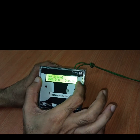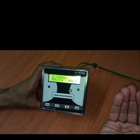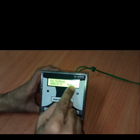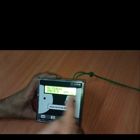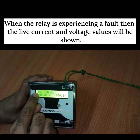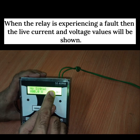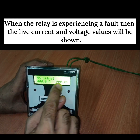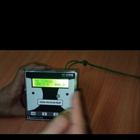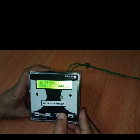So the first page gives you a snapshot of the relay performance, and when the relay trips, it will show the type of fault and relay trip will be written here. Another unique thing is that when the relay is experiencing a fault, it will show here that this relay is sensing this fault, and the live current and voltage values will be shown. And when the relay eventually trips on the fault, here the relay tripped signal will come. So this is the first page.